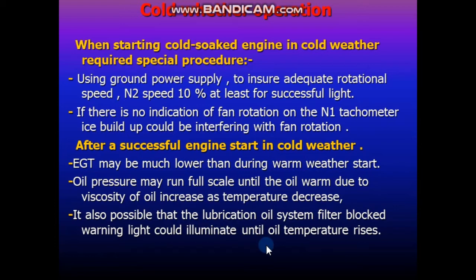When you see the indication that the oil system filter is blocked, that means the oil system is in cold weather. So you have to wait until the temperature of the oil rises. After that, the warning light of the blocked filter will go out.